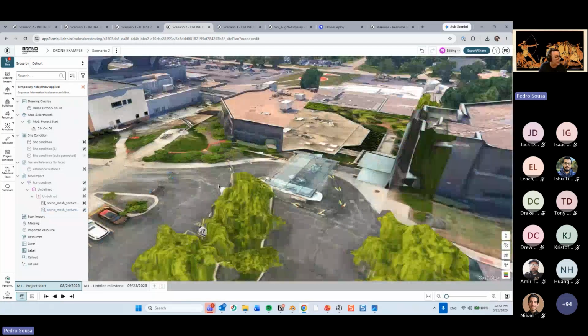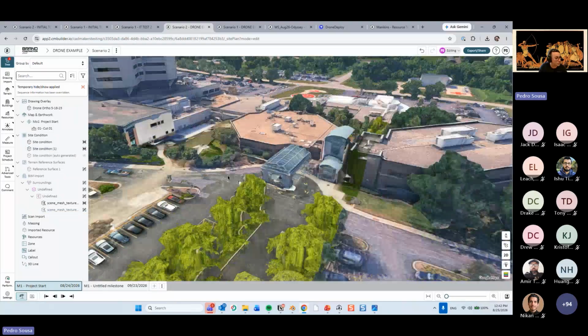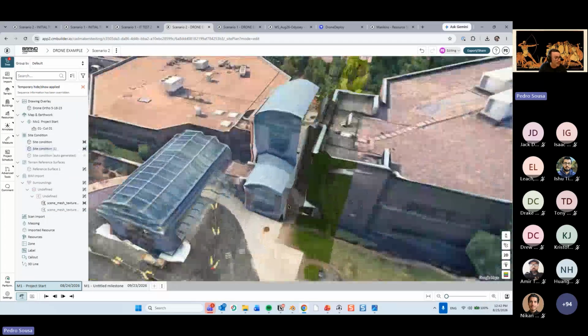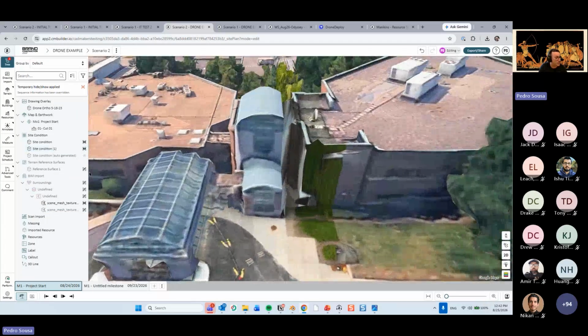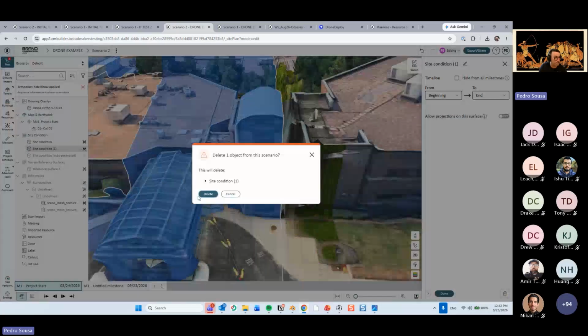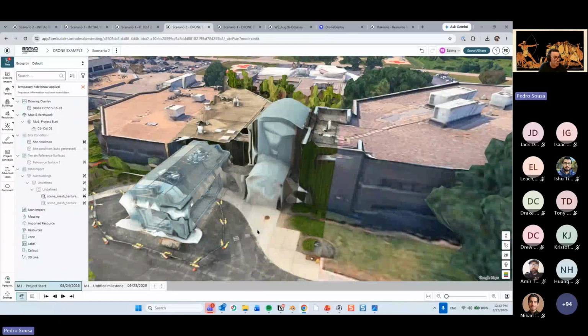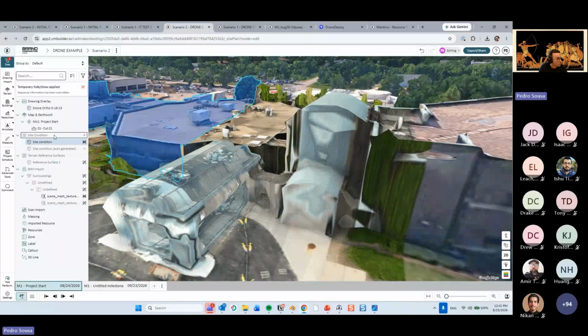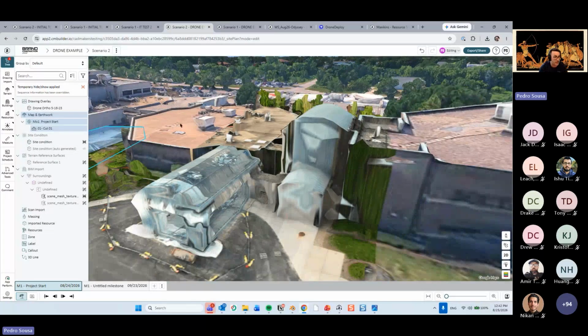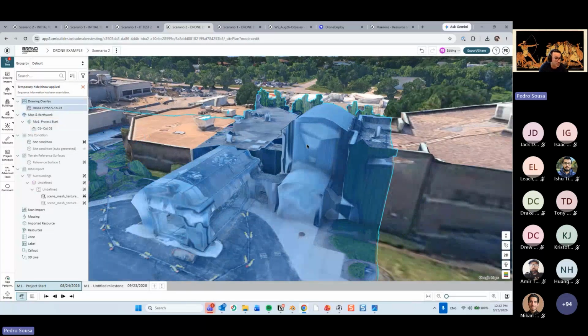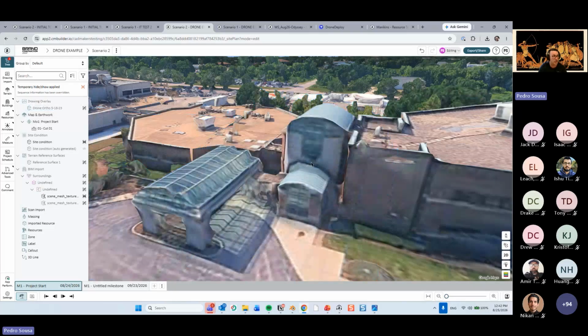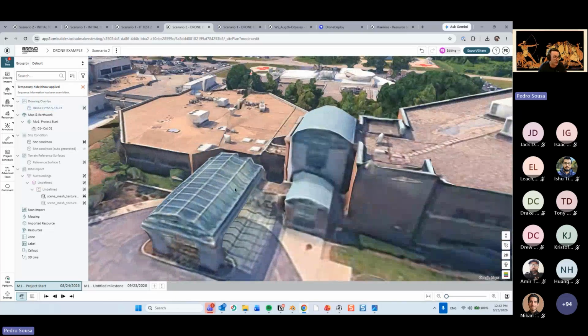And also, let me just show this again. One thing about the drone: whenever you project this image on the shapes over there, like on the Google Maps model, you'll be projecting a new image from above. The software doesn't know what to do with the vertical faces, with the facades. So it's creating this melting kind of thing going on over here. But when I hide this, that shows the proper image from the background, from the site conditions over there.